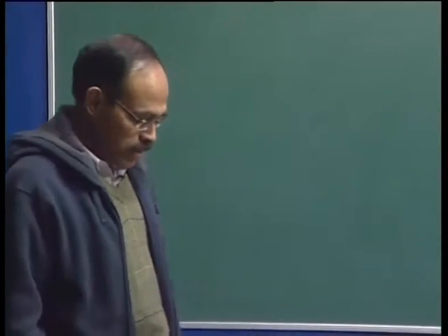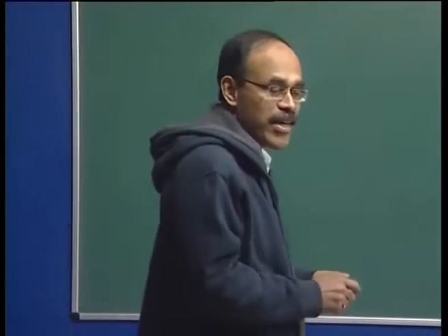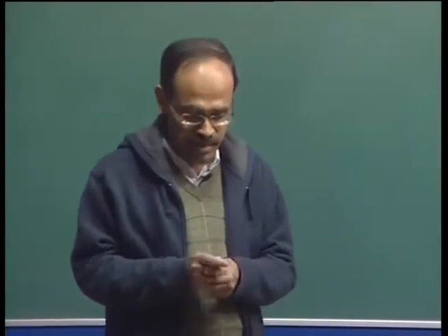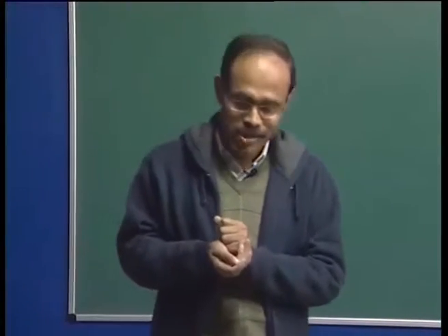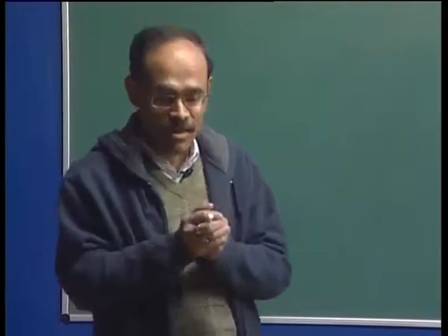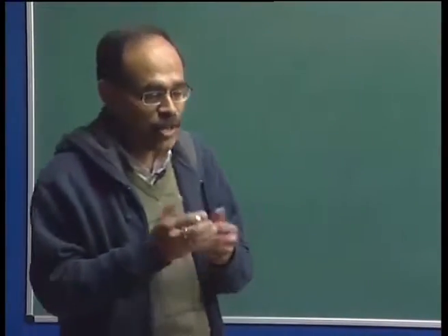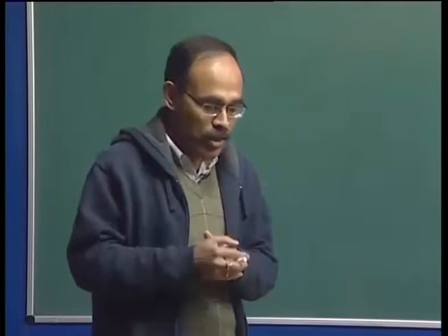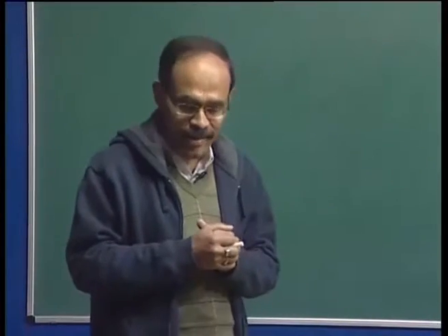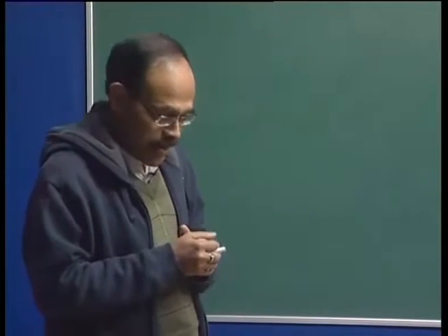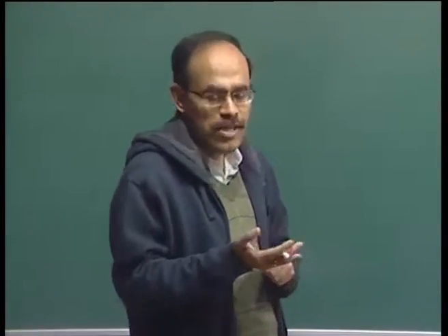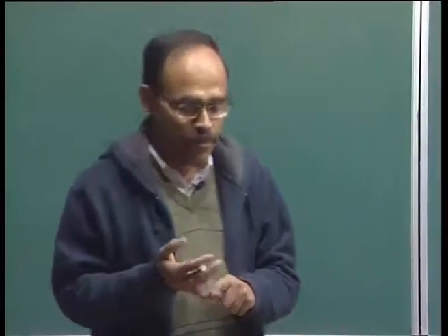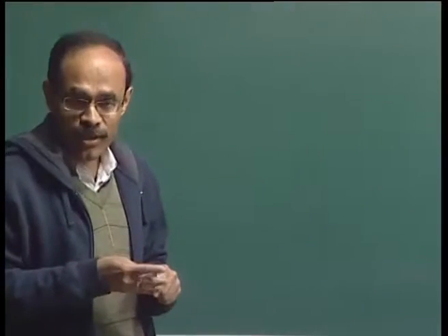So, what we have seen is that the motion of the fluid or the flow of the melt in a steel making reactor such as ladle, tundish, mold or a converter is the consequence of various kinds of forces, and consideration of these forces give us the necessary framework to develop the dynamic similarity criteria. And I have indicated that in systems where inertial forces, gravitational forces, viscous forces and pressure forces are only relevant,